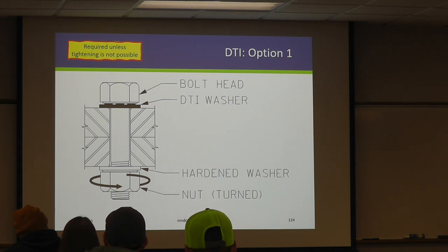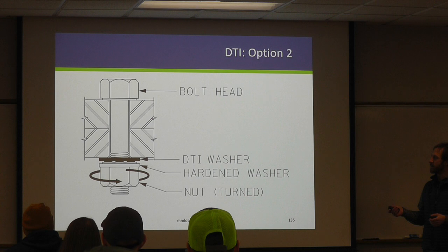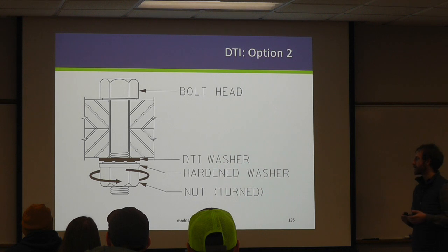So you'll get some pushback. I mean, it's probably gotten better now because we've clarified this in the spec, because it becomes a two-person operation. This is the required operation unless they demonstrate it's not possible. If it's not possible, we do allow the DTI to be on the turn side, but they have to insert a hardened washer between the nut and the DTI. This is primarily out of concern that if they let it rattle too much, you can grind down the protrusions. Pretty low probability of it happening, but it could happen.